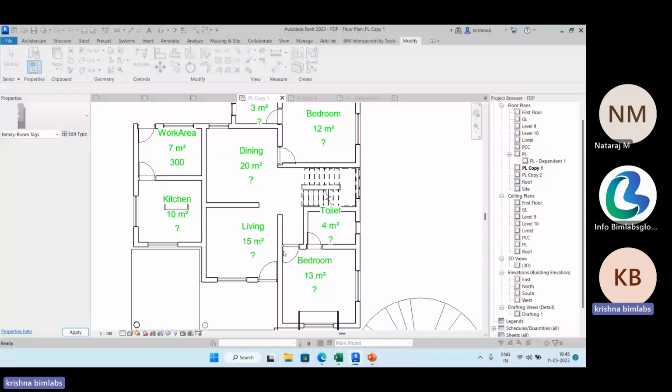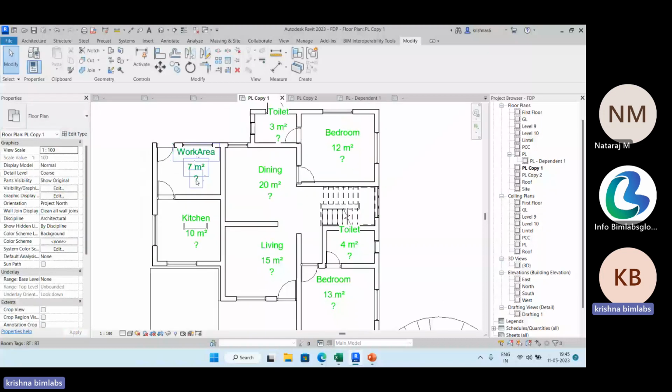Overwriting the existing version, you can see the name area is there. This is a newly created parameter, right? The dimension is a newly created parameter which is not there in this particular Revit template. So we have created it as a shared parameter. Now the next step is we want to convert that shared parameter into our project parameter.